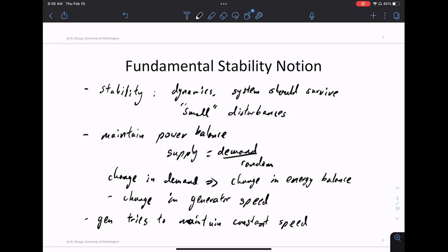Instead of nature giving you this equation, if you really look at this equation, it is a physical equation that has to do with torque, but that's your classical physics equation. You cannot touch this one. All you can do is track the frequency. If you have renewables, stored batteries, electric vehicles, solar, and all that, that still causes energy imbalance. How that shows up to the generator, to the solar panel, that is your problem to design that signal. Nature is not going to provide you that signal anymore. Conservation of energy does not show up in this sort of rotating frame.